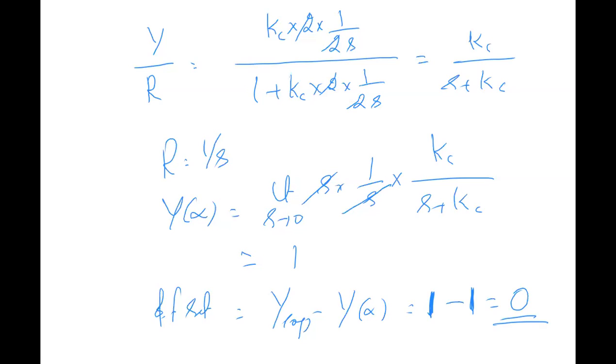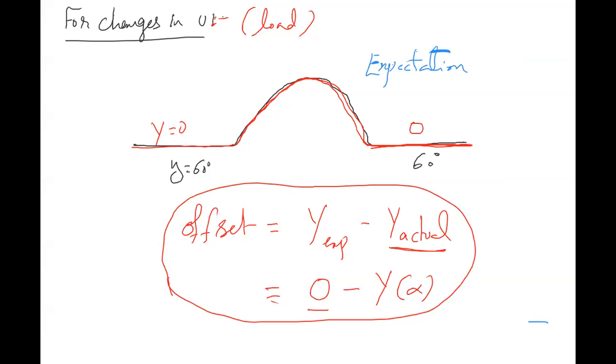So just take 2 minutes and everybody digest the answer. Is there anything wrong? Why is the expected 0? Because when there is a change in the load, this is the response that you are expecting. For changes in the load, your steady state will be disturbed, and the controller should bring it back to the previous steady state, which is 0. Clear?